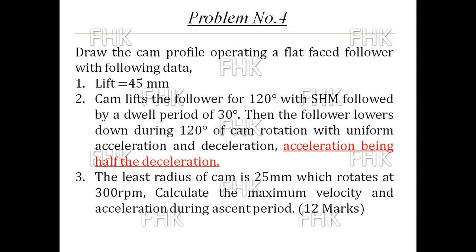I read the problem statement in front of you. Draw the cam profile operating a flat face follower with the following data. Lift is given as 45 mm. The cam lifts the follower for 120 degrees with simple harmonic motion, followed by a dwell period of 30 degrees. Then the follower moves down during 120 degrees of cam rotation with uniform acceleration and deceleration, but the acceleration being half the deceleration. This is the new concept that we are concentrating on in today's session.